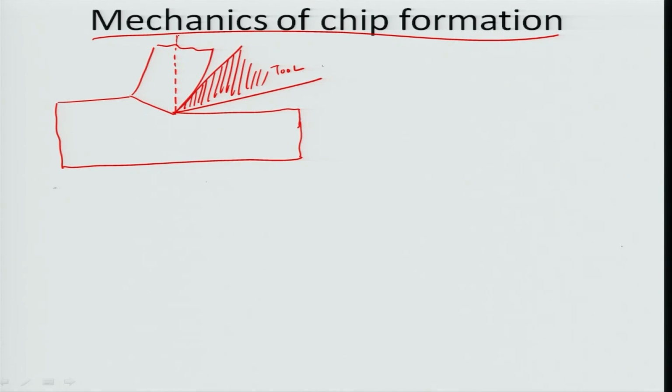So, this angle is really the angle that the tool's rake face makes with respect to the perpendicular, and I call this angle alpha. I think I had just illustrated earlier how this rake angle or rake face can be defined, and obviously you have a certain direction of the chip velocity, which is the direction in which the chip is moving.